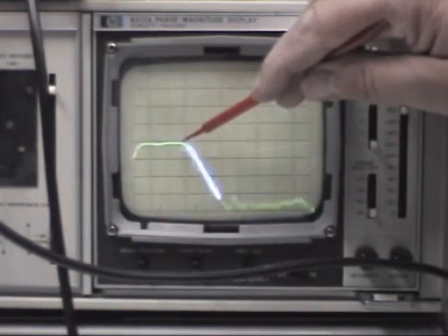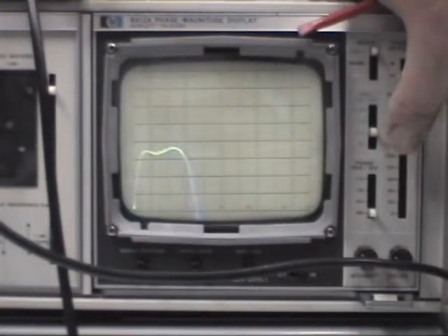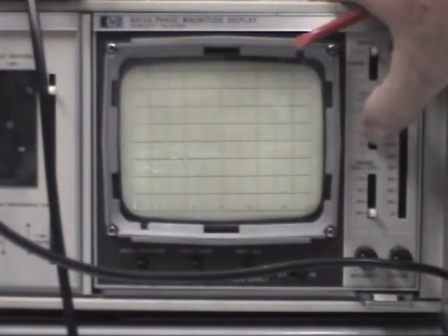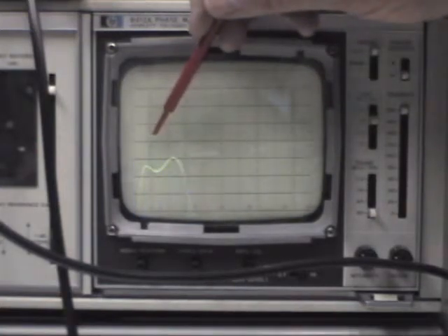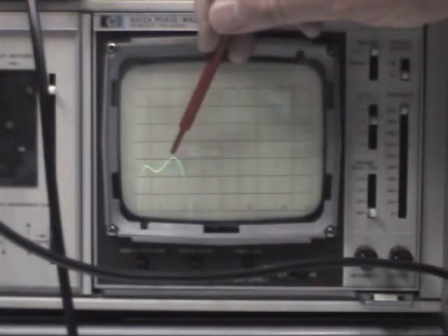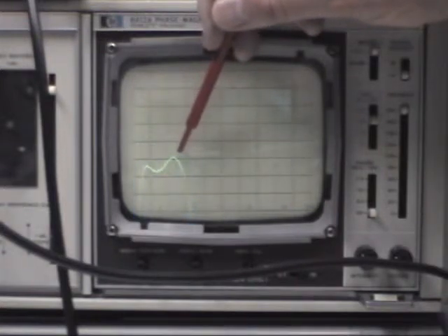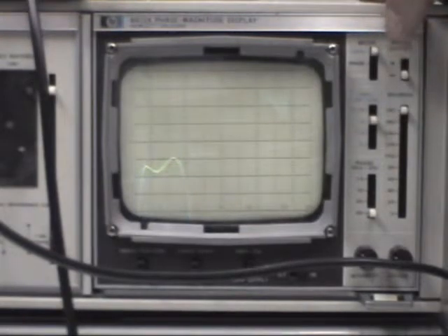Let's take a look at the insertion loss right here. We can do that easily by just changing the dB scale. Now that's 2.5 dB per division. That's 1 dB per division. And if you notice, we started right here. So this is 1 dB down, right around 14 megahertz where we want to start rolling off. We're about 1 dB down. So that's about right. That's not bad at all. So we had about a 1 dB insertion loss.